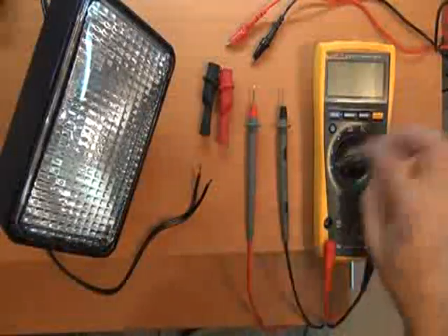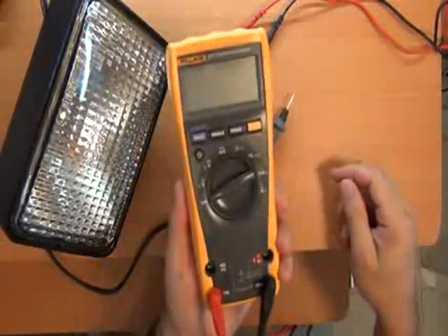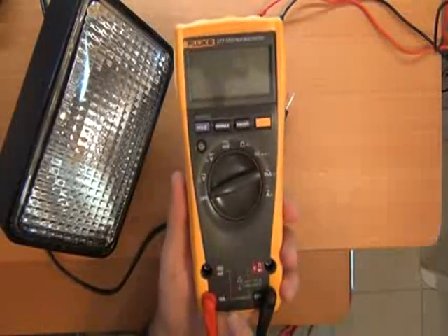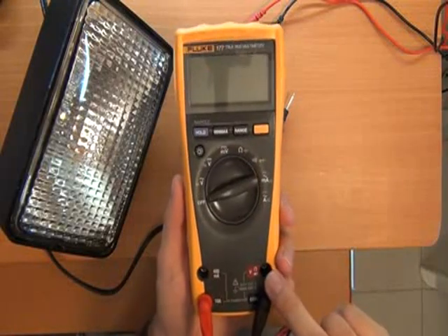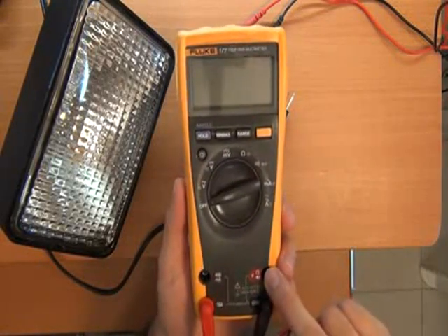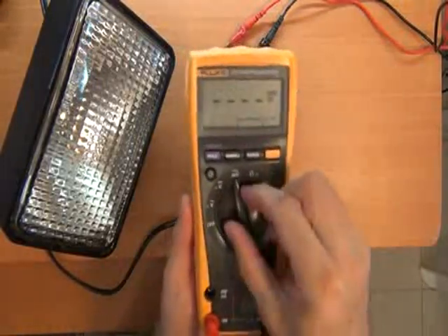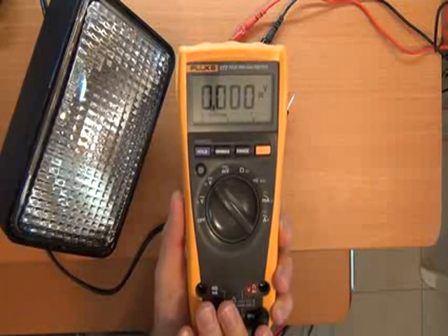Okay, so first of all, the first thing we need to check, we've got our multimeter. As I said, hopefully you've got a multimeter which has separate inputs for measuring current. It's far safer that way. Potentially if you have shared inputs on your voltage input, then if you make the wrong selection while you've got things cabled up, you can cause a short and blow things.